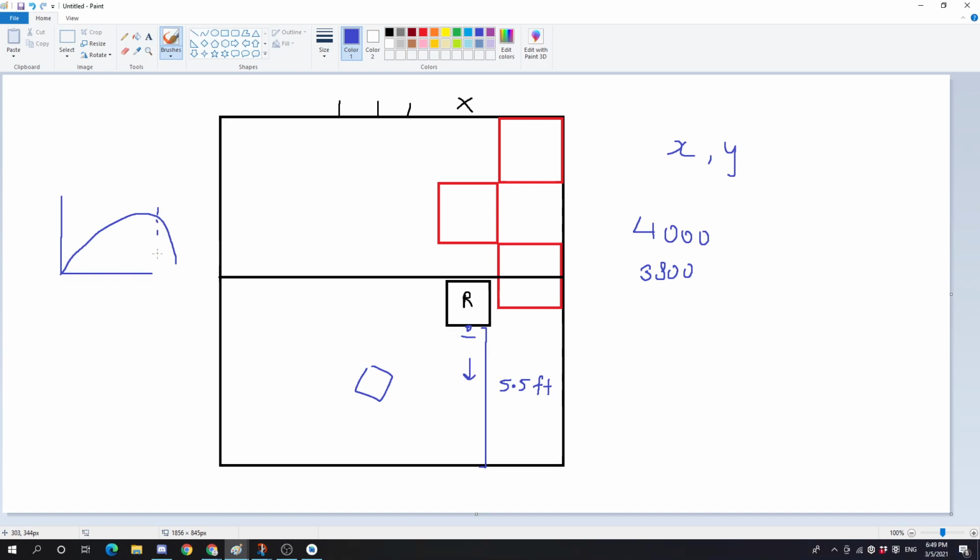You're at that point where the ring is going to dip. So let's say over there, instead of making the ring hit the high goal over here, we want it to go up and then curve down into the high goal. Obviously that gets a bit more inconsistent, but let's say our shooter can do that. So let's say at 3.5 feet, our shooter revs back up to like 3,900 RPM. And then at 2.5, it's at 4,000. And then at 1.5, it's like 4,075, right? I'm just making some random numbers.